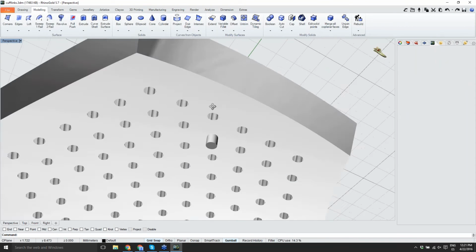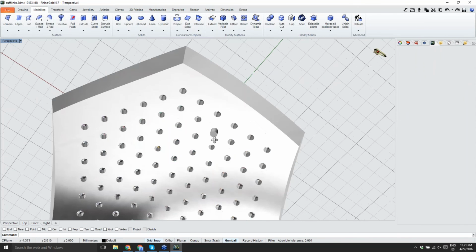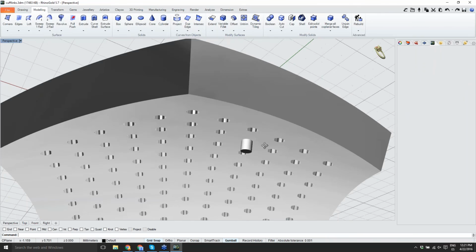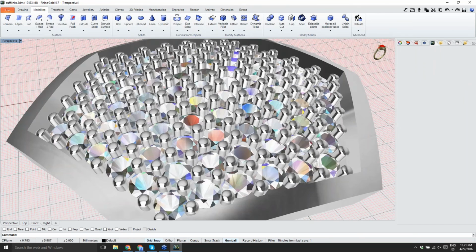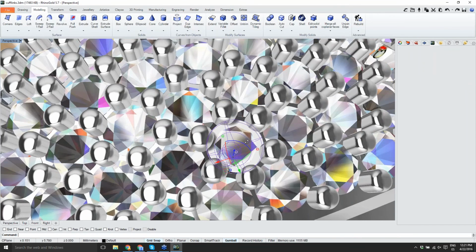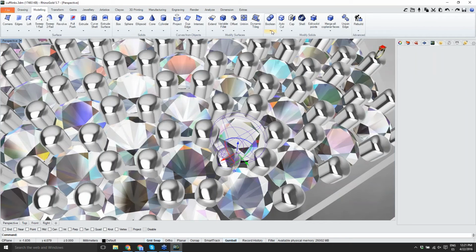And now, when we want to remove the cutter and the Boolean operation fails, under the Boolean submenu we have the Shake Objects tool. So Shake Objects allows us to shake my cutter in order to move it randomly.